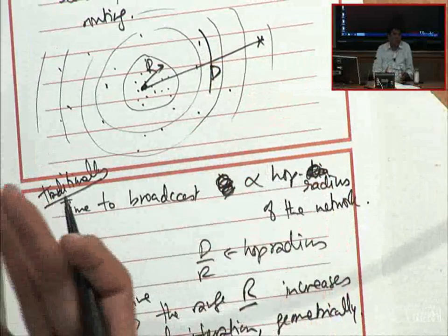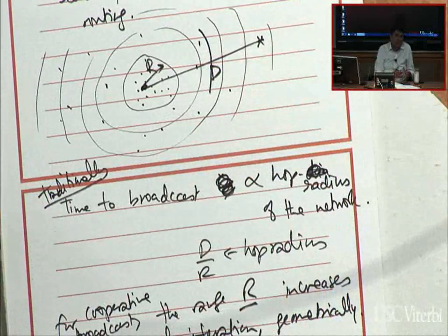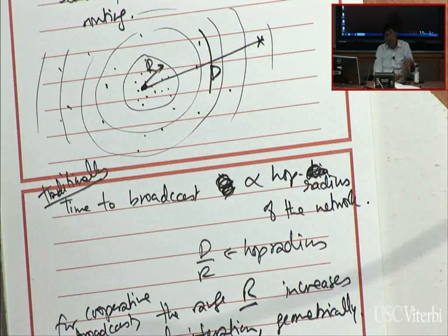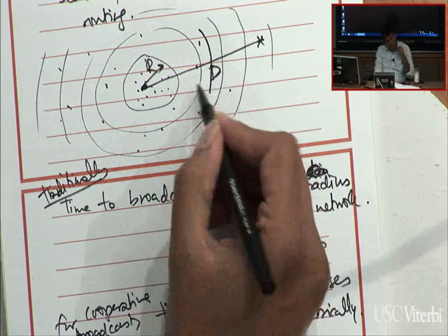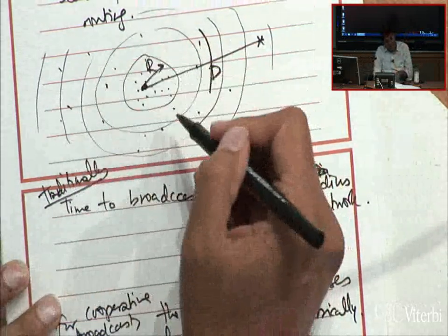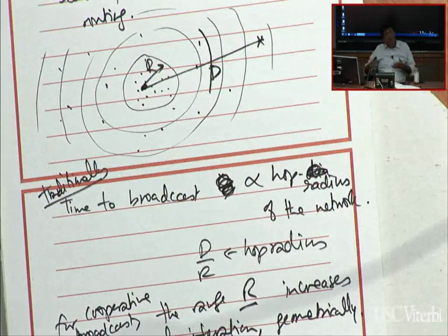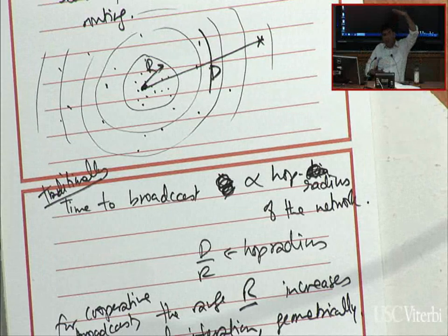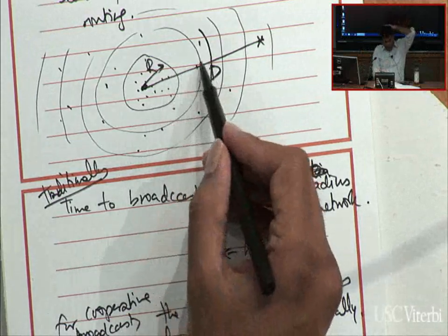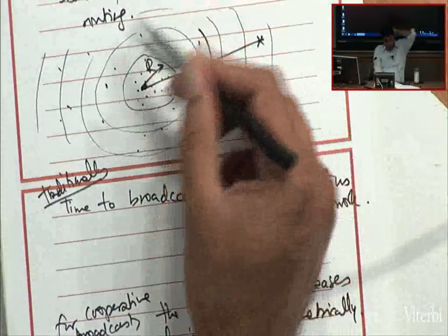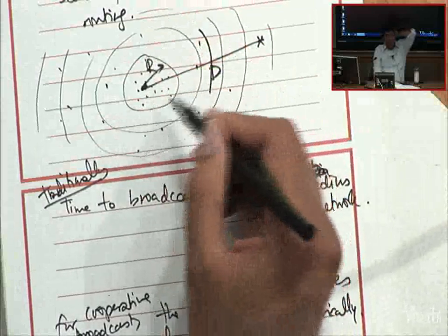Right? That's the whole benefit of trying to do cooperative synchronized transmission, is you're improving the SNR. And if I improve my SNR, effectively I'm improving my transmit power, if you want to think of it that way. So if I can boost up my transmit power, it's going to reach farther. Right? And so because it'll go farther, now I will get more nodes in that second round. Now all of the nodes that are in that second round are synchronized, and they're going to transmit at an even larger transmit power, because the number of nodes that I'm having within that radius is quadratic in the radius, right?